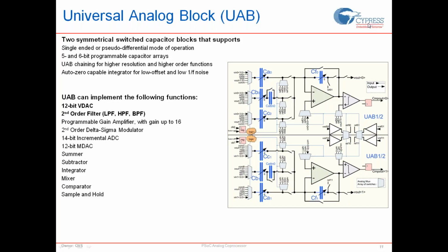So you would pick a PSoC Analog Coprocessor when you will use an analog sensor. You need to read inputs from an analog sensor that require high precision and high accuracy. So there are no top 3 reasons, but the main reason is to read high precision, high accuracy analog sensor inputs accurately and process that data and send that to a host for an application that you need to use that data for.